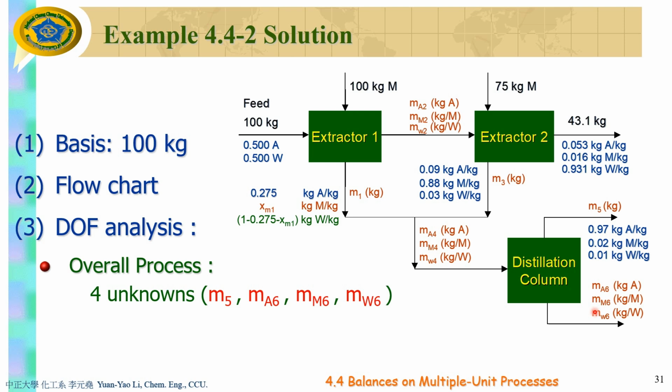Do you need to convert volume to mass or mass to mole? No, you don't, because all the streams are liquid, so they all use mass, kilograms, and you don't need any conversion. The fourth direction is physical constraints. You already have this one, so it's not counted into the unknowns. So these are the 4 directions you need to know.